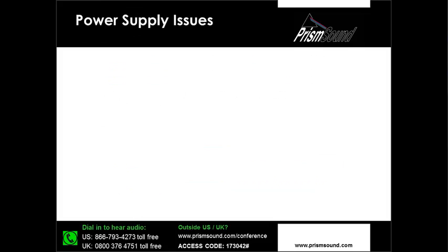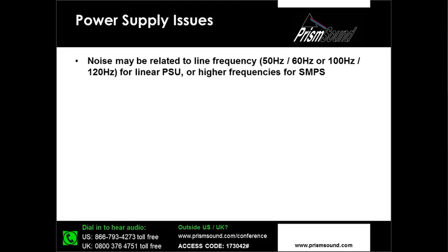A couple of other issues then. Well, let's look at the power supply. It's reasonably well understood that if we're not careful with our power supply design or our local decoupling from the power supply, we may either directly introduce mains related components into the audio signal, or perhaps we might get some kind of modulation artifact, power supply modulation occurring at either the mains frequency or harmonics thereof. For switch mode power supplies, of course, running at much higher frequencies than mains, much higher than audio frequencies, we may see other intermodulation artifacts, noise and interference products appearing in band.